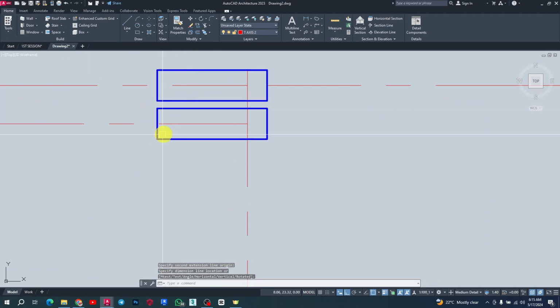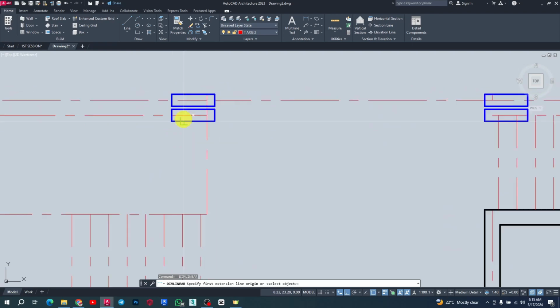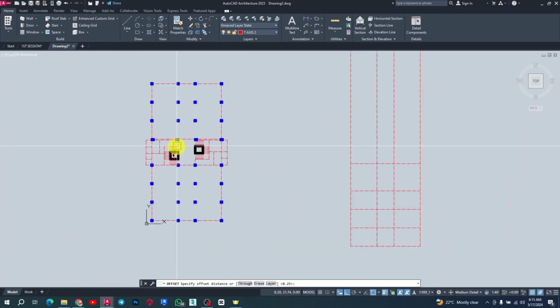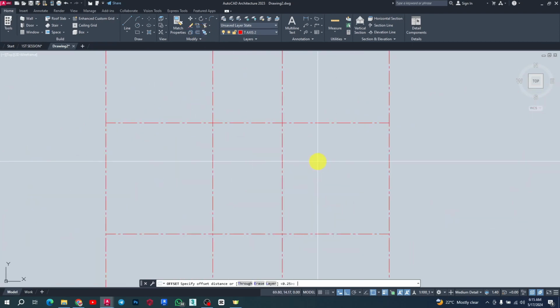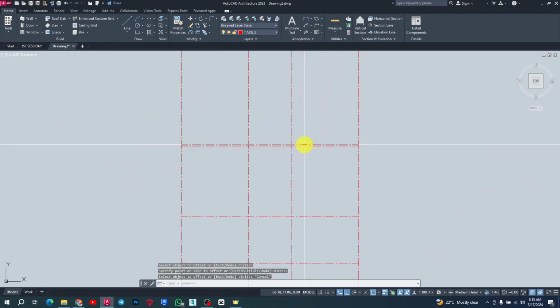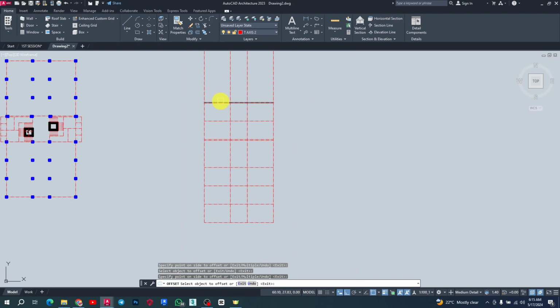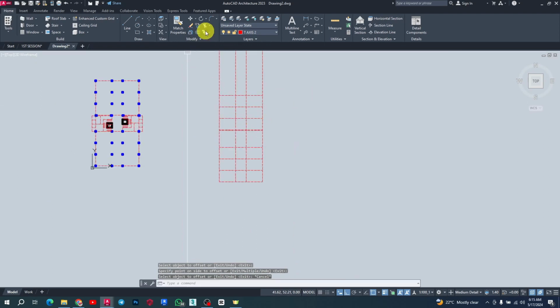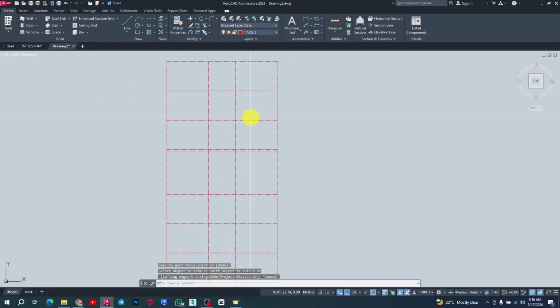So I have to add 20 plus that, so it gives me 25. That will be the expansion, so I'm going to have 0.25. You type enter, and then you extend the line going back to my 5.15 again. So I go up, I think 3 times, right? I'm going to click, hold down, and then trim this one. If I go this way, I cannot trim it, so trim that, and then we are good to go.